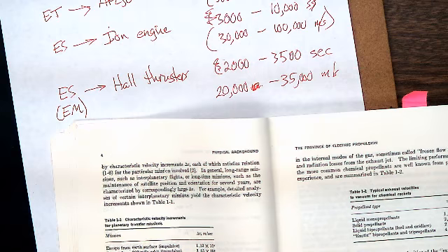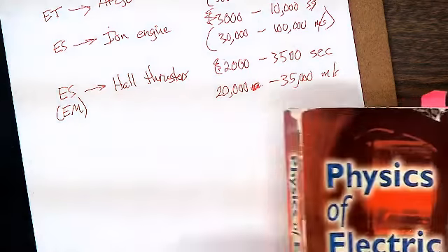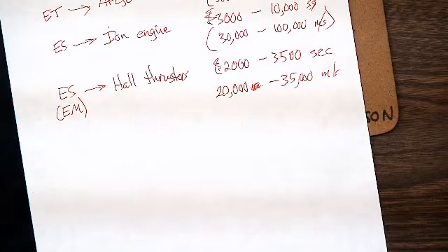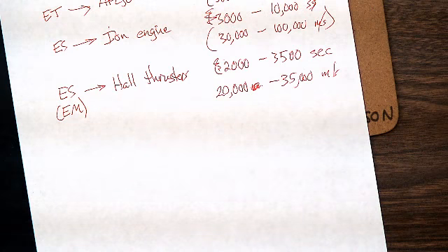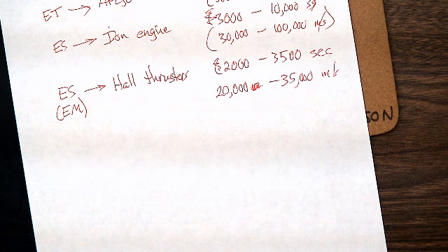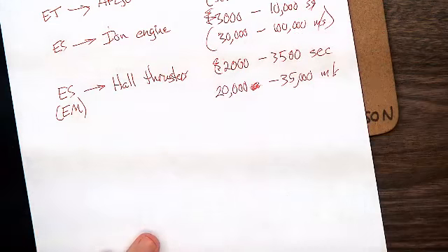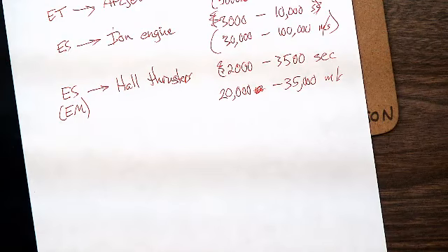And so if you want to have a practical payload mass, you need to have the delta V over Ue term in the rocket equation be higher, right? So you want to go to a higher Isp to increase your mass fraction, which will get you more payload to your destination.